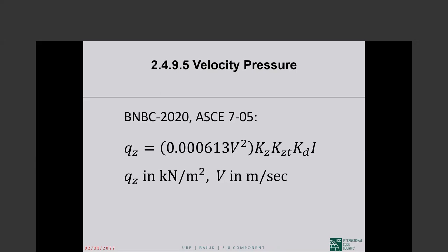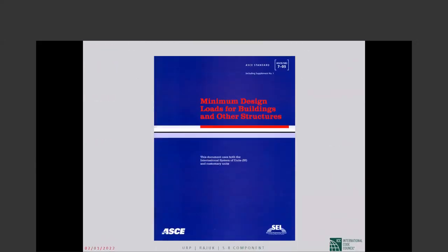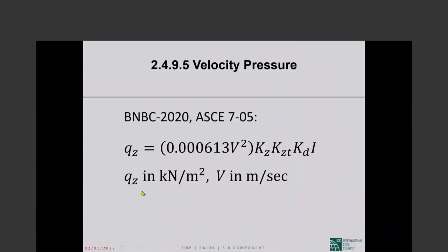We say z feet, here it is z meters, I don't know. Anyway, so Q at a height z above ground level is essentially 1/2 rho v squared. This is from basic physics: 1/2 the density of the air multiplied by the wind velocity squared.